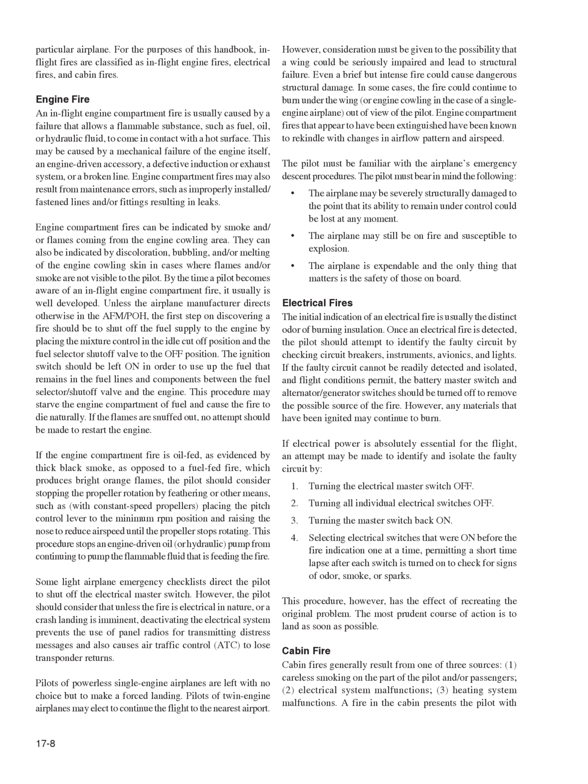The pilot must bear in mind the following. The airplane may be severely structurally damaged to the point that its ability to remain under control could be lost at any moment. The airplane may still be on fire and susceptible to explosion. The airplane is expendable and the only thing that matters is the safety of those on board.